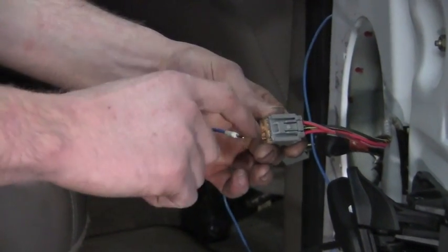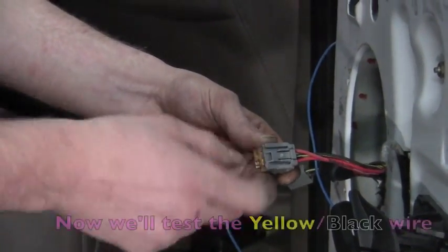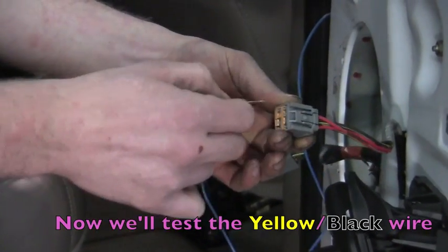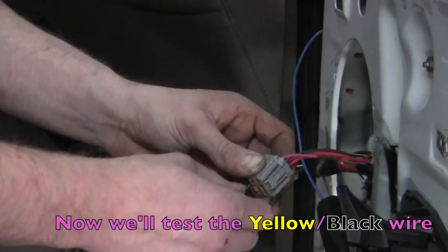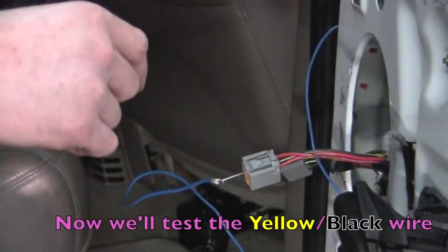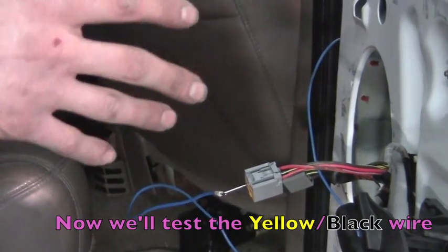Now I'm going to take the back probe that we had on the red and black wire out of the connector, and I'm going to put it on the yellow and black wire. Okay, now that I have that there, I need to go up to the front on the driver's master switch and do the same thing on the same wire.